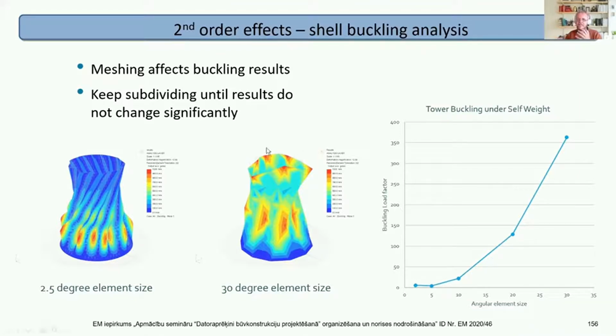If we just split these flat elements down, we'll just get larger flat surfaces in more detail. When you're splitting these curved surfaces down, make sure the split results still give you the curved surface, otherwise you'll get localized buckling, flat surfaces, and so on.